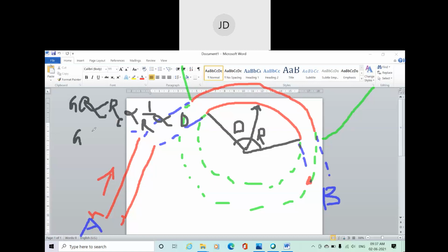So we can write that grade compensation is directly proportional to the degree. In the last class, for different gauges of railway track, broad gauge, meter gauge and narrow gauge, different grade compensation values were mentioned: 0.04%, 0.03% and 0.02% respectively, with respect to degree. You can cross-check the last class recording or notes, or refer to any reference book. These things were already discussed.